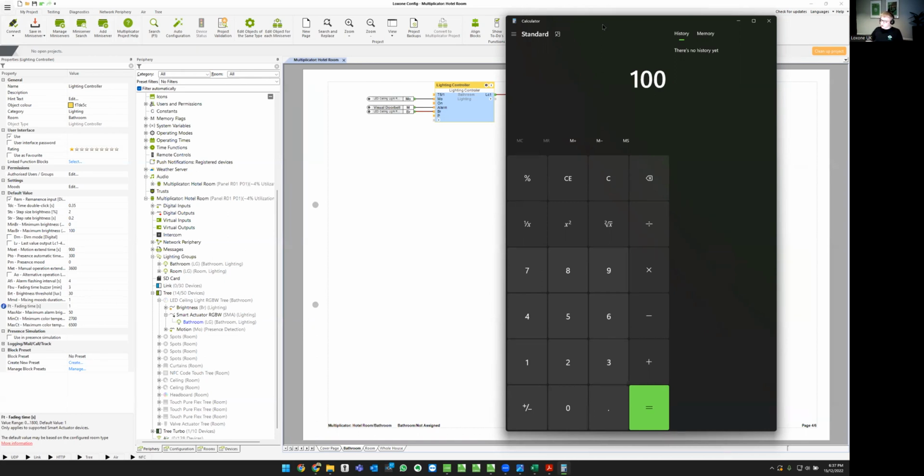Now, let's say that you've got a restaurant with, we're going to use a nice round number of 20 speakers. That's 2 kilowatts. Now, let's bring that down. And so we know that that's 2 kilowatts. Now, restaurants are generally open 12 hours a day, again, a nice round number for us to work with. So 2 kilowatts constantly running at 12 hours a day is going to be 24 kilowatt hours per day.